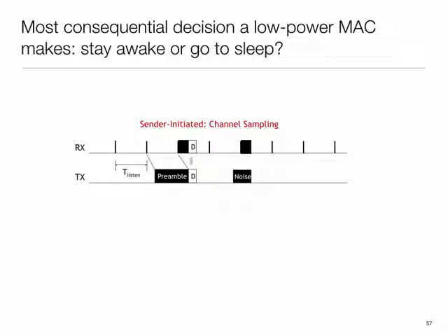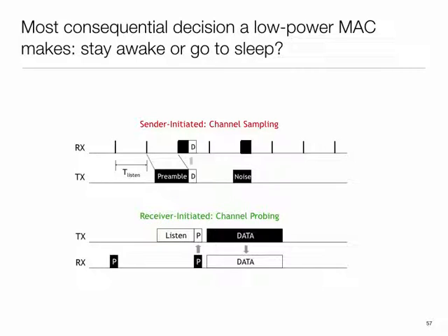The problem is that if that probing is done like the way you were describing, which is just look for some noise, some signal on the channel, then any transmission by someone else may wake you up. So we want to avoid that situation. With receiver initiated, that problem is eliminated. There are no spurious wake-ups because it's actually a genuine probe.